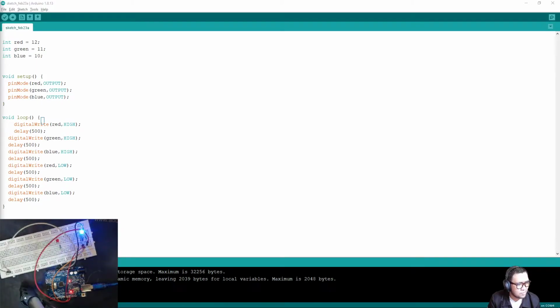So let's just rotate our Arduino. To rotate the Arduino, you will be using the button R. Click on the Arduino, then press R. So we will be connecting the ground wire to this whole lane here. Then it's colored as black.